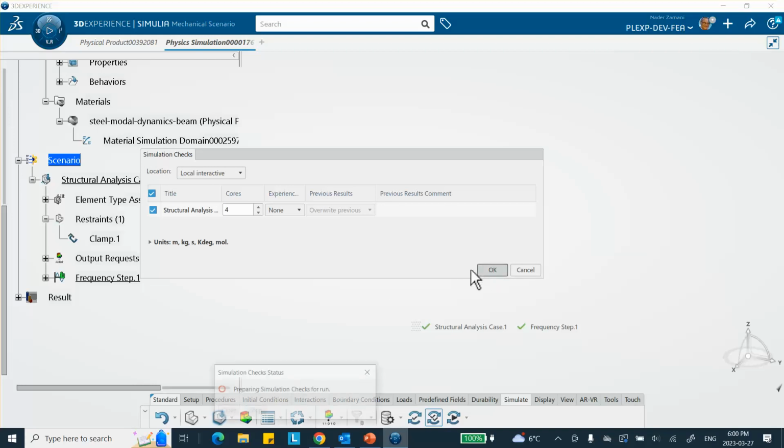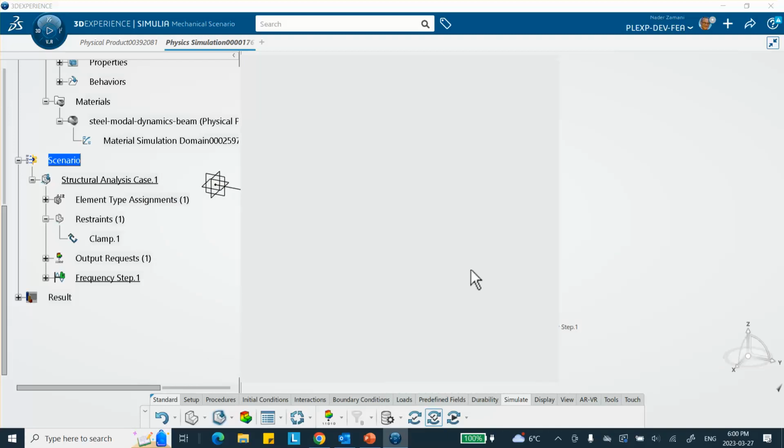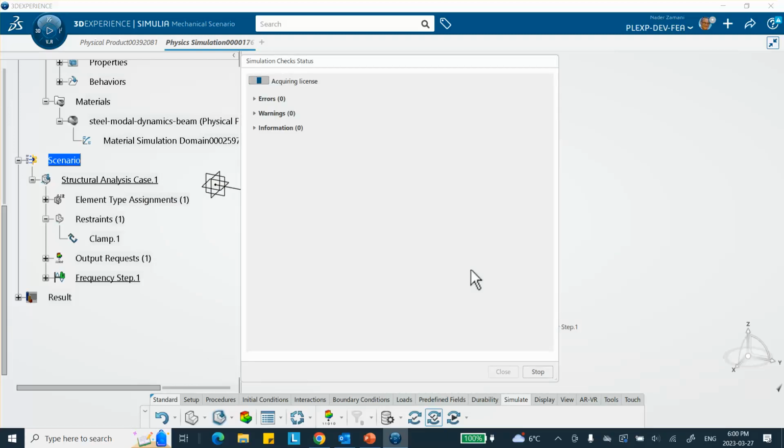Okay. And we're going to make a run. I don't anticipate any problem. We're going to make a run, and we'll have the 10 extracted mode shapes and modal frequencies. Now, of course, some of them may be torsional and things like that. In fact, what I'm going to do later on, I'm going to restrict the motion of this beam completely out of plane and from out of plane so that all the modes are bending modes. So let's see now. It did.